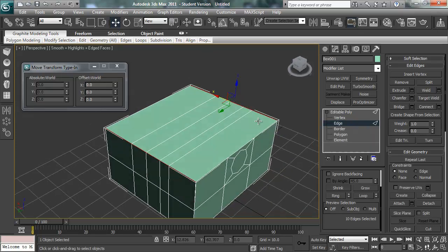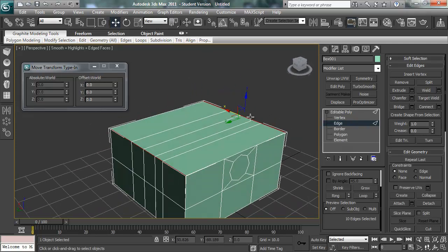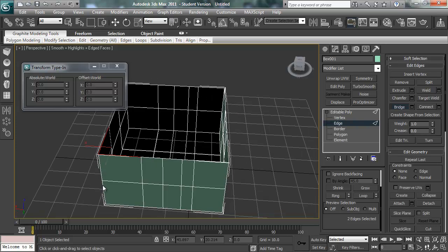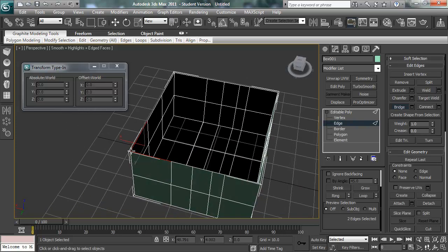them together. Now do be aware that bridge will sometimes sort of not work. That'll be because you're trying to do something which is, I guess, the equivalent of impossible. So I wonder if picking that will, no, that should work actually. Maybe picking these two will not work. Okay, so bridging those two will not work because they already share a vert, and it gets horribly confused.